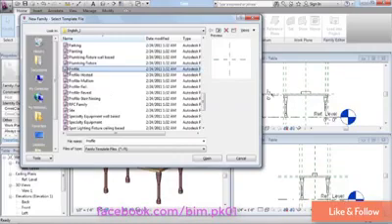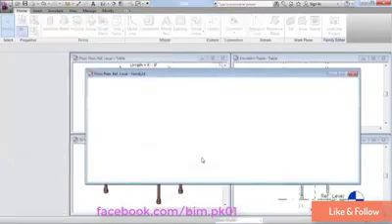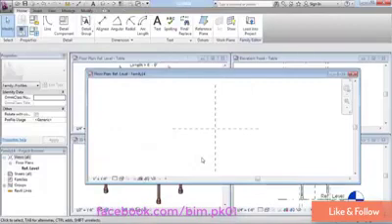For our case, to just create a profile that we're going to use in a geometric sweep in a family, we can simply use the simplest one, the simple generic profile family. So we're going to go ahead and open that up, and it will open up a single view, and you're looking at what should now be the familiar 2 reference planes, center front back and center left right. The intersection of these 2 reference planes is the insertion point of the profile.